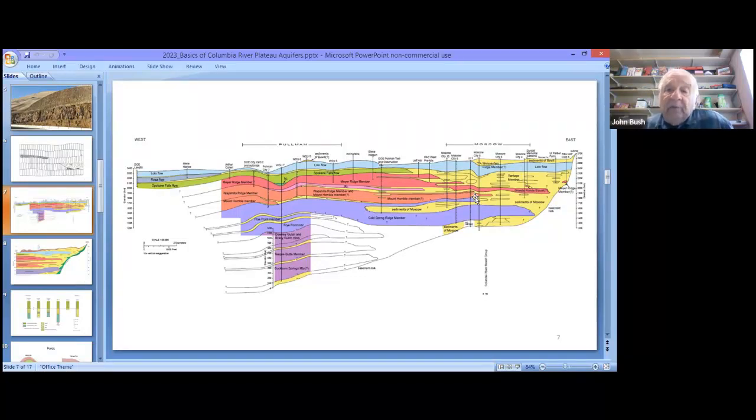I got to look at the samples, and the important part was looking at the details of the basalt. It's very tough to get people interested in that because to them it's just black basalt chips. But if you look at the chips of this 125 foot zone, particularly here in the R2 in the red, it turns out there's 2 or 3 porous zones, 2 or 3 interflow contacts. So that zone of 125 feet is really either 3 different flows or 3 spread outs.